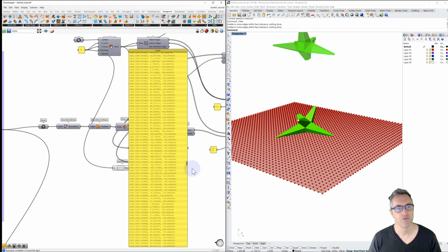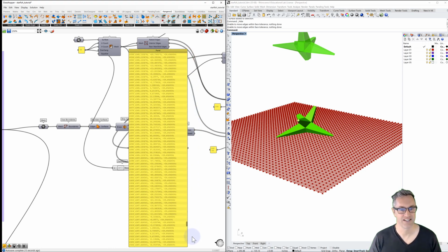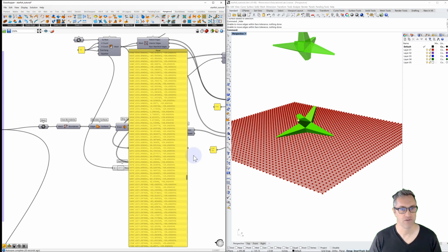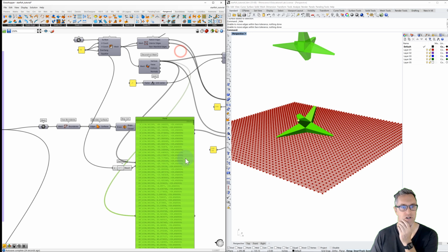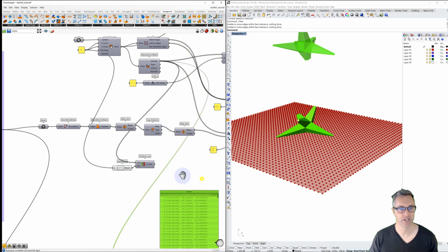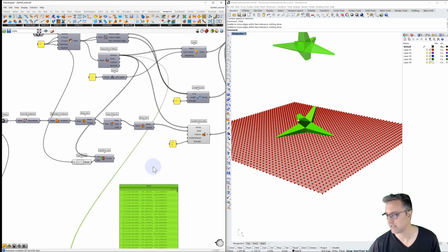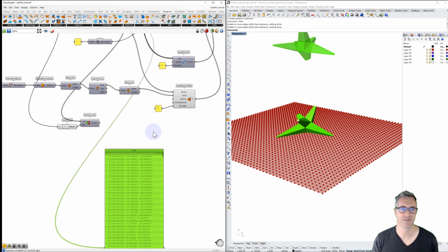All right, so what we're getting is a list without any divisions. So by partitioning the list, we're going to basically break our list into the row of points. And that's what we want to use to fix our mesh. Basically, we want to use the points along the 4 edges. That's what we're trying to get to.